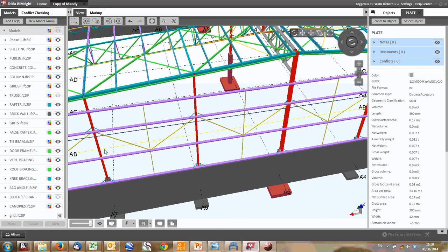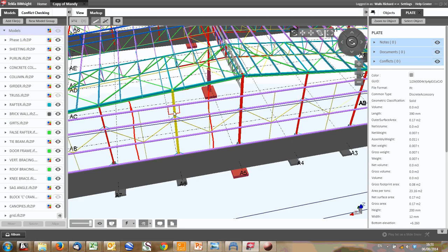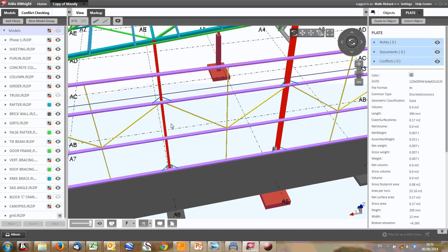Well, this is halfway between each column. So if I mark it up, hopefully I can draw here. There you go. So it's an area like that goes to this column in the middle. So all this would sit on that column. And that way you can very quickly get a load and design this column. You don't have to get lots of little point loads and have a very complicated analysis model. You can very quickly get an almost correct model. There you go. And you can design it.